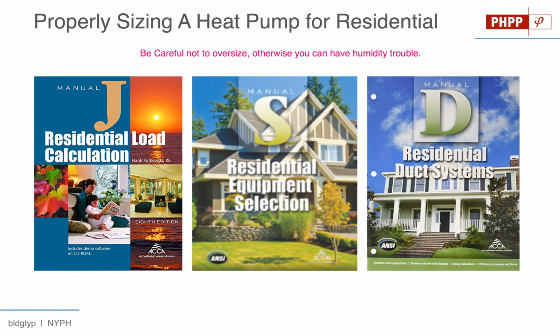And then there's another manual that I don't remember the name of, because we never use it, for actually designing your registers and diffusers as well. These would be the appropriate methodology and the appropriate reference standards to use when you're designing and sizing the heat pump system for your passive house building. Do be careful not to oversize these heat pump systems, because then you can run into significant cooling issues.